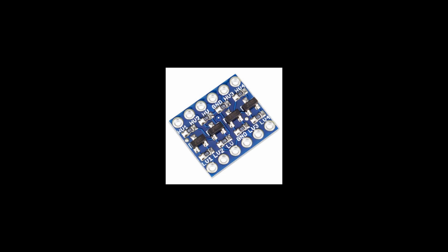These shifters are usually bidirectional, so they can also be used to allow the Pi to trigger a 5 volt input with its 3.3 volt outputs. Typical level shifter module: a level shifter, also known as a logic level converter, will take the 5 volt signals and convert them to 3.3 volt. This allows the Raspberry Pi to read outputs from sensors that are powered from 5 volt.